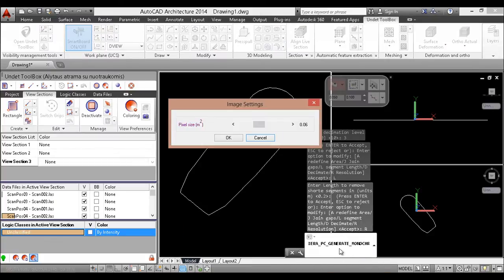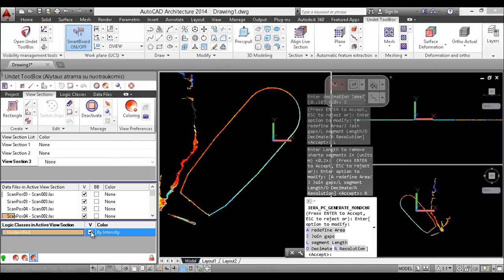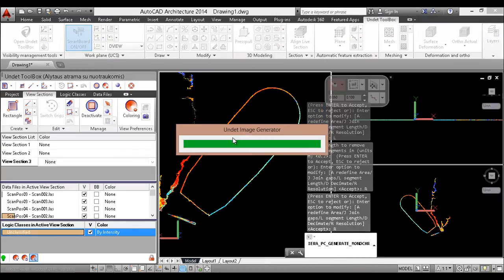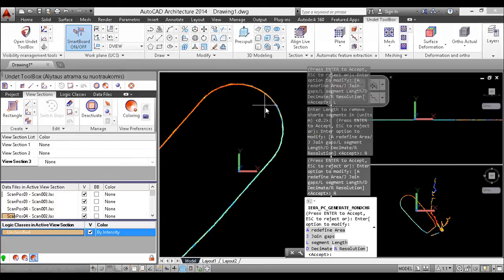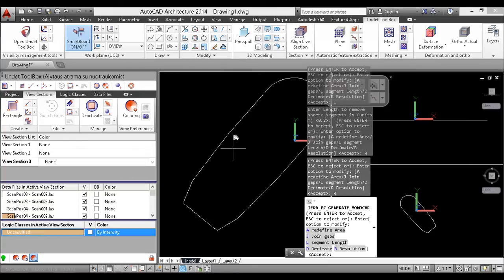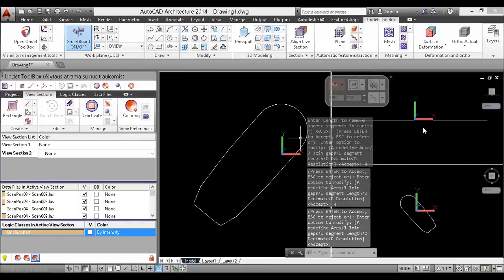The resolution value is basically about your precision. So it is the tolerance, the error, it is half of this value, so 6 cm would be 3 cm. Let's make it 0.4, so my tolerance now would be 2 cm. And just before, you need to turn on the point cloud to define this value. Okay, 0.4 centimeters. Nothing is changing in general, so it is good enough. And let's accept it as our profile.